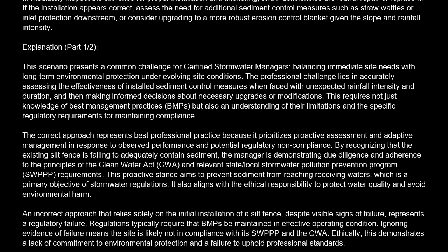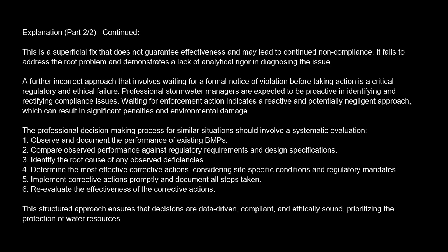Another incorrect approach that involves simply adding more silt fence material without addressing the underlying cause of failure, e.g., improper installation, inadequate anchoring, or overwhelming flow, is also professionally unacceptable. This is a superficial fix that does not guarantee effectiveness and may lead to continued noncompliance. It fails to address the root problem and demonstrates a lack of analytical rigor in diagnosing the issue.